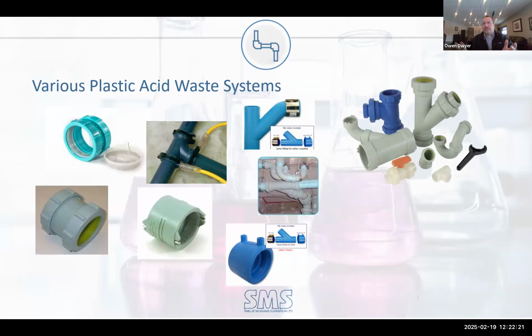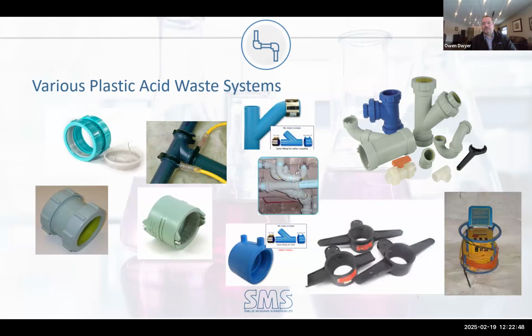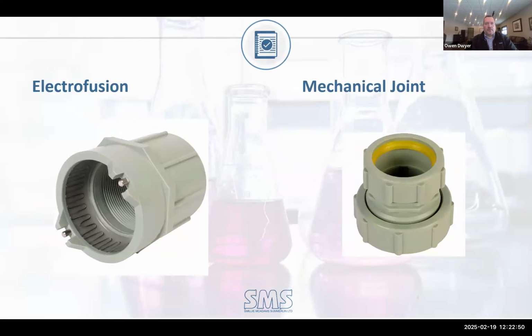So, for example, if the building is an old building and you're reconfiguring an old geography room to now be a science class, and the school had no sprinklers, you could not use polypropylene in that application, so now you're down to choosing either PVDF or a glass material. So PVDF meets flame and smoke. It does have a flame and smoke listing. I hope I've conveyed that in a manner that's understandable. Special provisions for polypropylene is what you have to think of.